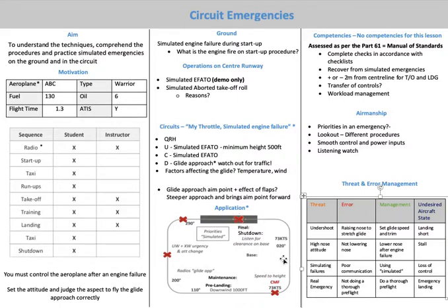Aim point of the field, airspeed 73 knots, aspect. Checking if you're too high, too low. Listen for your clearance on base. Do your 300 feet checks as normal, and then do your shutdown checks. So F-triple-M: fuel off, mixture, mags, master all off. Remember, these are touch checks. You're not actually going to shut down the engine.